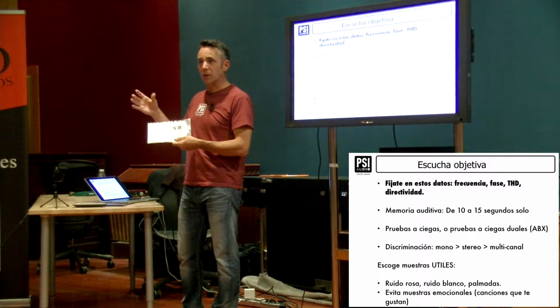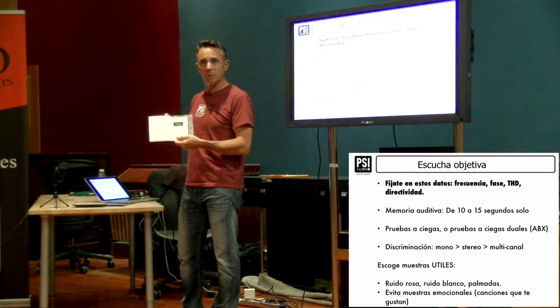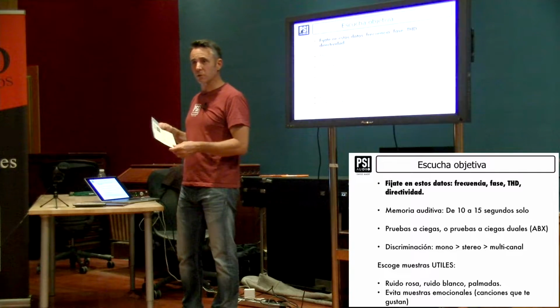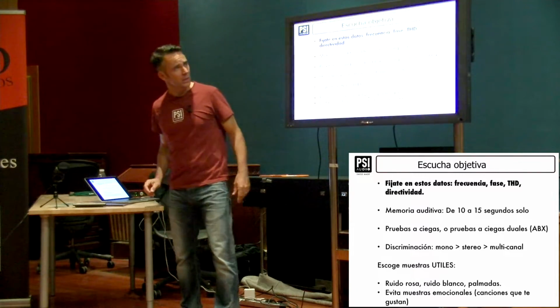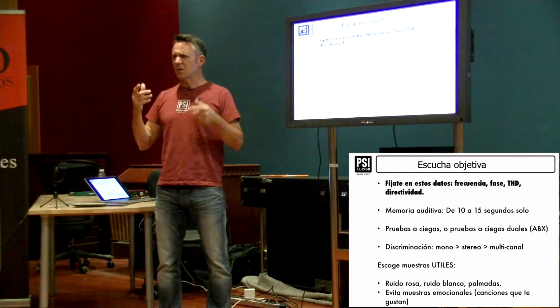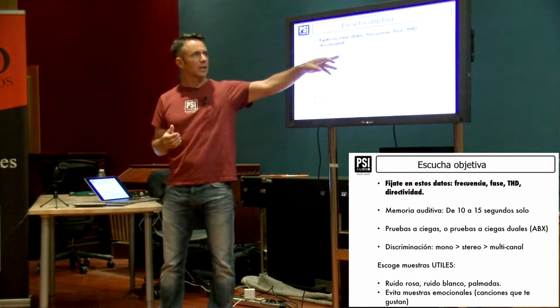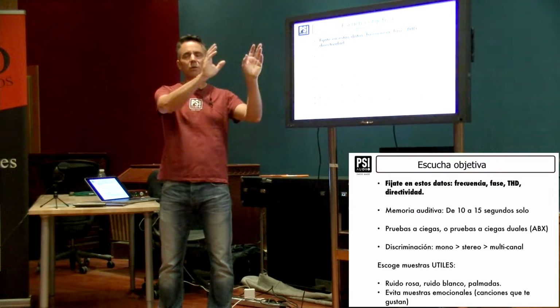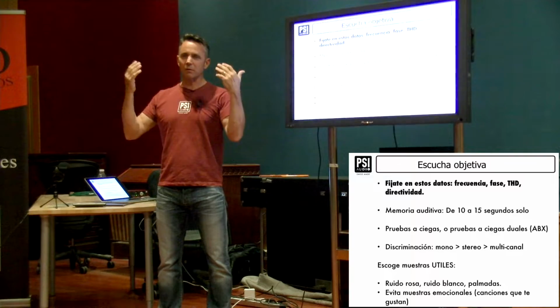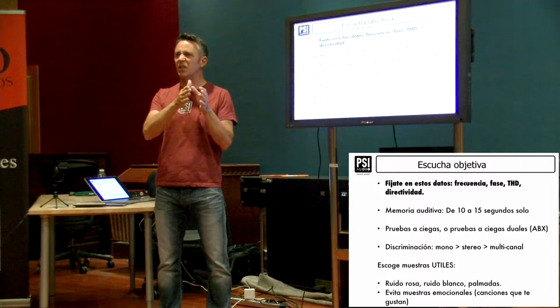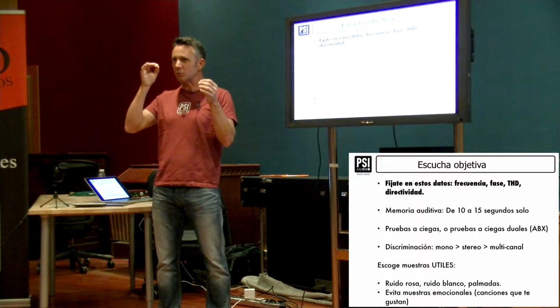So you can ask for a calibration curve to make sure that it corresponds, at least the frequency response. Otherwise, you might be getting anything, or check it when you get home. Then when you check, you can only remember sound over 10-15 seconds. So if you listen to something in one place and the next day you listen to another monitor, it's very, very difficult to know which one, unless it's really your mix in the same room and you do remember it.